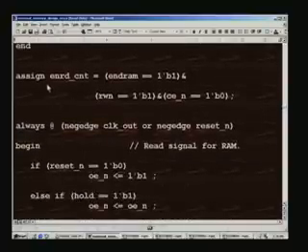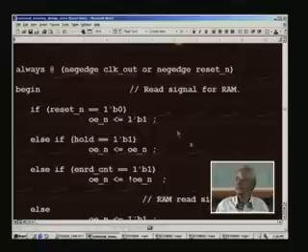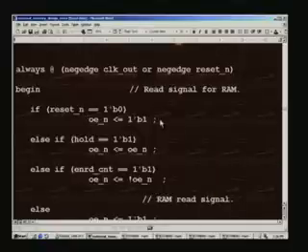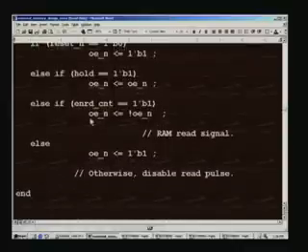So we have an enabled read counter, and that is based on enabled RAM being high, and read write is in read mode and chip is enabled. For this condition, what it does is read signal for RAM, that is this is the read signal we generate for the external RAM access, and if it is reset, this is active low, therefore it is taken to a safe state here, and for hold it is preserved, whereas for enabled read count we invert that OE.